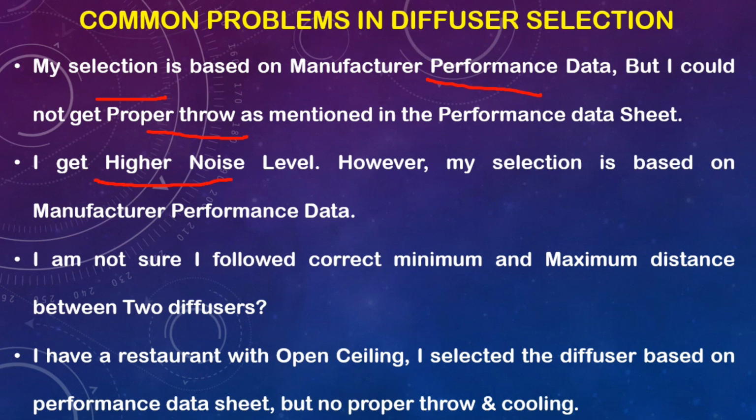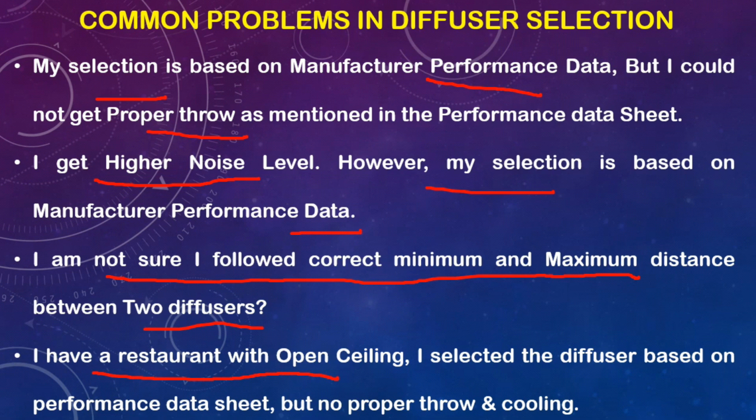Or I get a higher noise level, however my selection is based on manufacturer performance data. Sometimes we ask, I'm not sure that I followed the correct minimum and maximum distance between two diffusers. Similarly, for a special kind of project, you can ask a question like, I have a restaurant with an open ceiling. I selected the diffuser based on performance data sheet but got no proper throw and cooling.